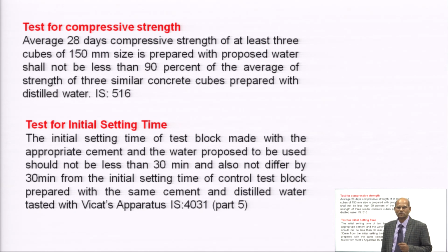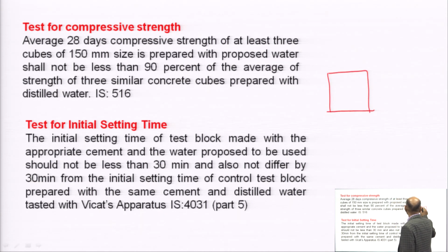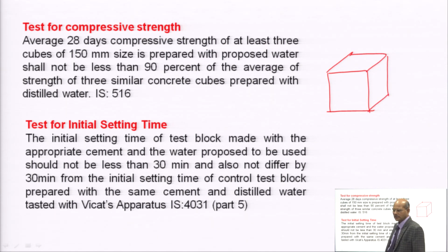And the test for compressive strength. Suppose we want to use the water and want to determine the strength criteria. What do you have to do? You have to make a cube of size 150 mm by 150 mm by 150 mm with the water which is intended to be used, and similarly make another 3 cubes.